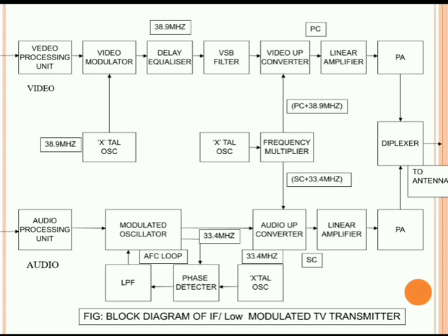That particular duplexer consists of one coupler DC1 unit, then an audio notch cavity, that is the second cavity, a 3 dB coupler, that is DC2, and audio notch cavity ANC1. In this duplexer, the isolation between the video and audio signal input ports is maintained, while the two signals are combined at the output port.